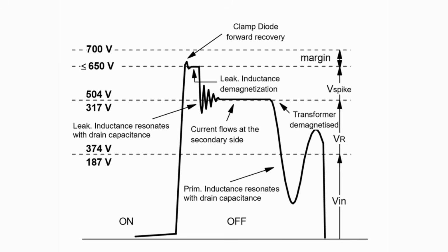So that's actually why you see MOSFETs rated for 650 volts or higher. Now I understand that that was a lot of information to digest and comprehend, so I want to review some of the important details and go over some things to help cement your understanding of the flyback converter. A lot of the details have to do with the operation of the transformer and the process by which a voltage gets induced into the secondary winding.